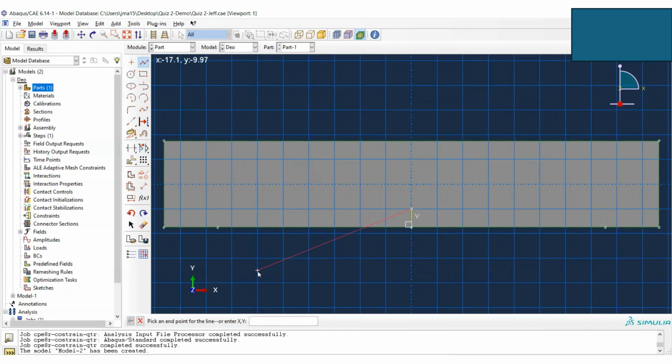Okay, let me press ESC, and then use create a circle, and we use this crack tip as the center, right? Then we draw here and make sure your point is on this point. My mouse, this white point, is on the vertical line. Now I have finished, and I cancel this one, and then I dimension it.